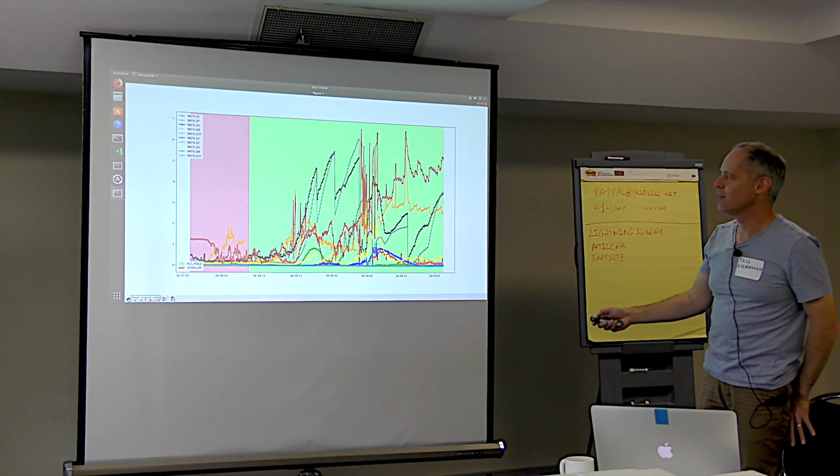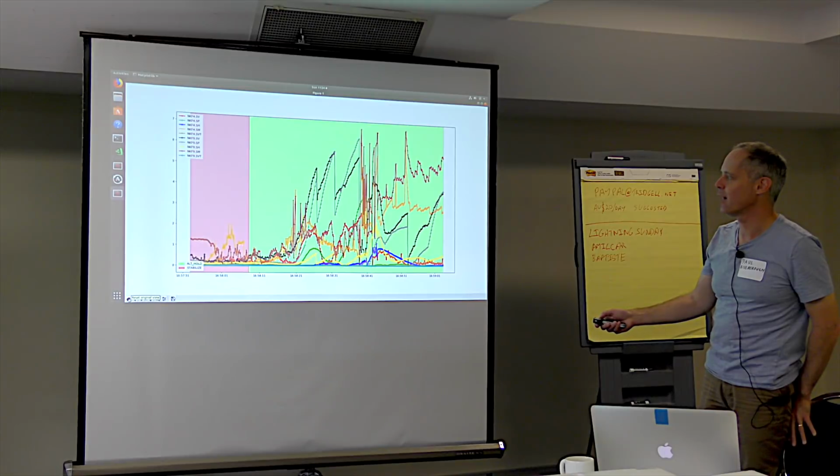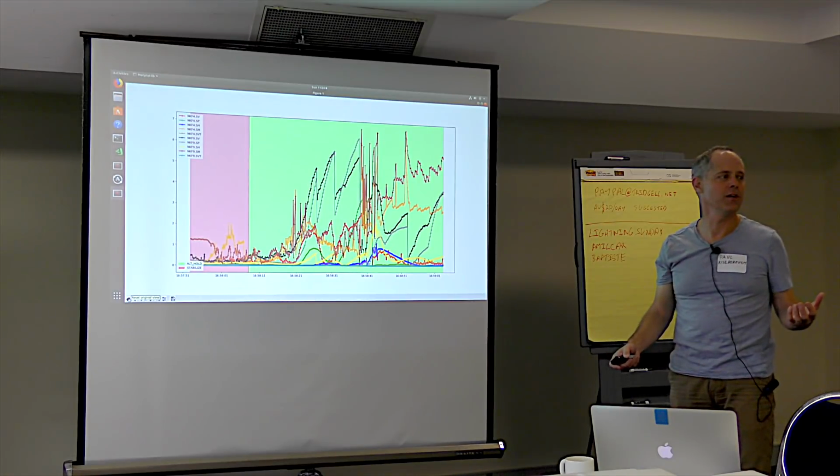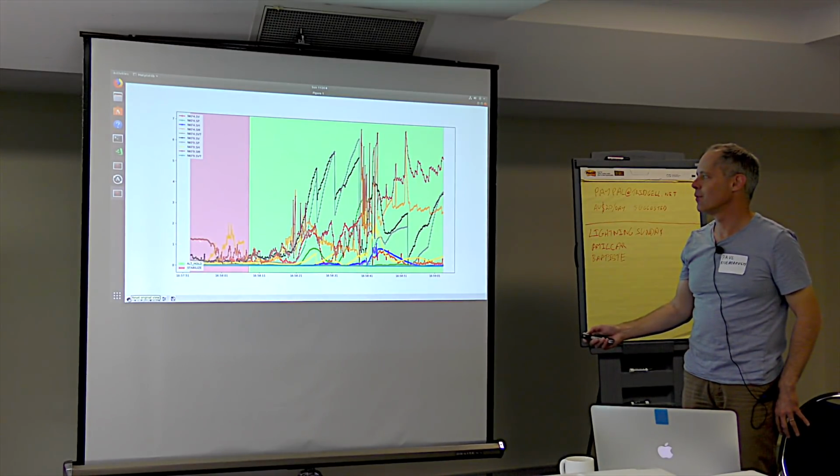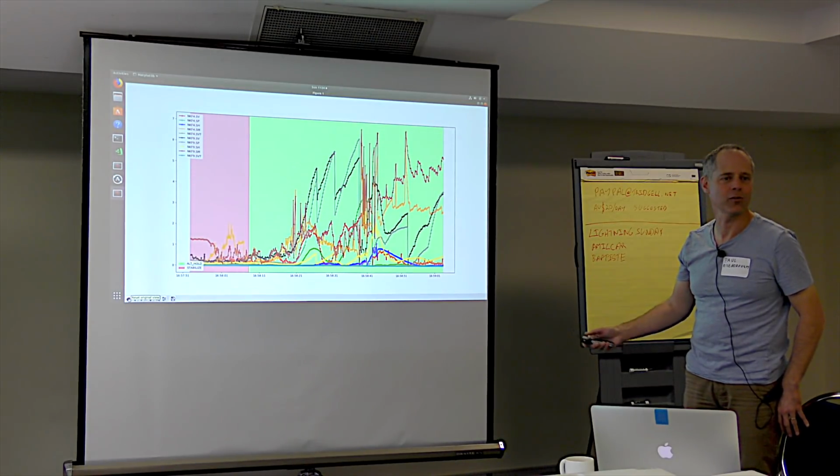And then we'll show you the vehicle does a rotation, and then the next magnetometer is failing. So that's a clue immediately. And you'll notice that this magnetometer is failing, then it passes, then the other magnetometer fails.